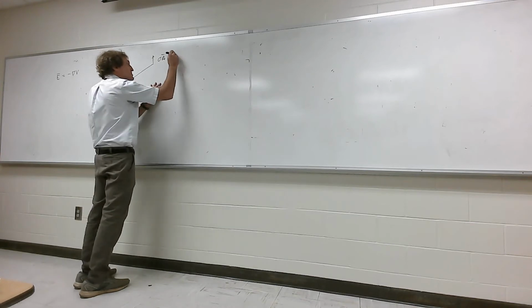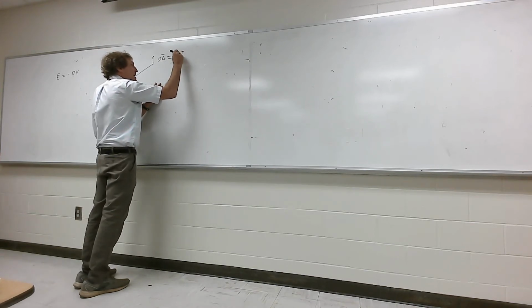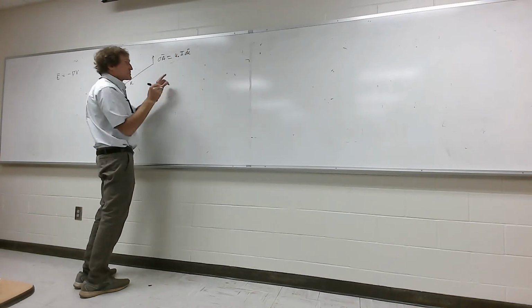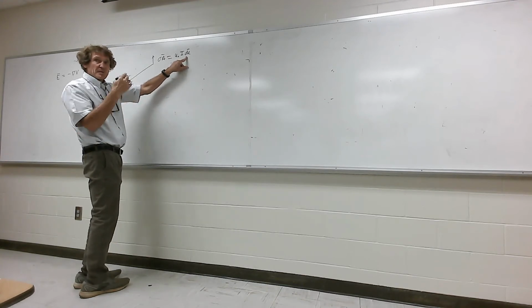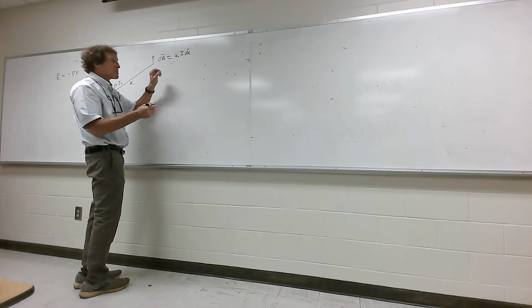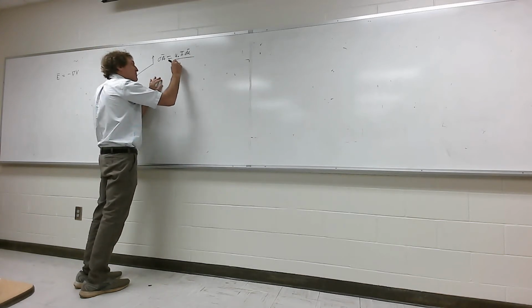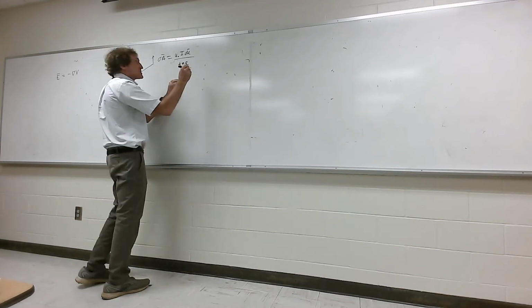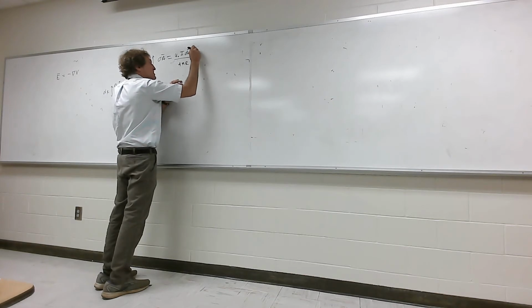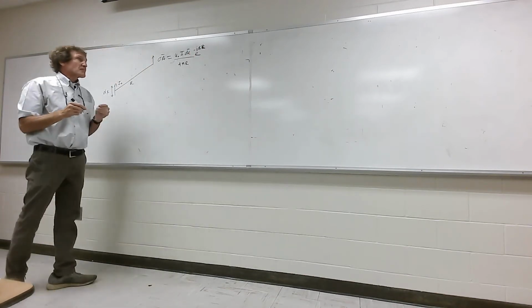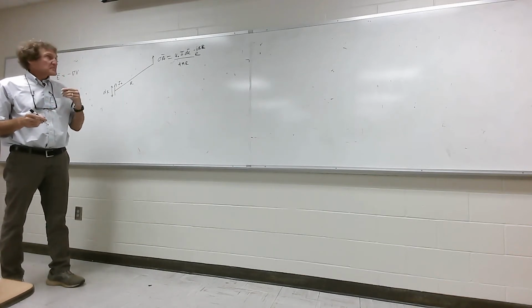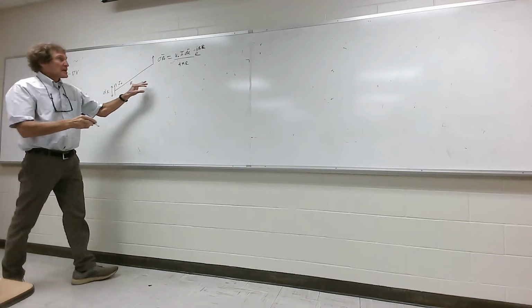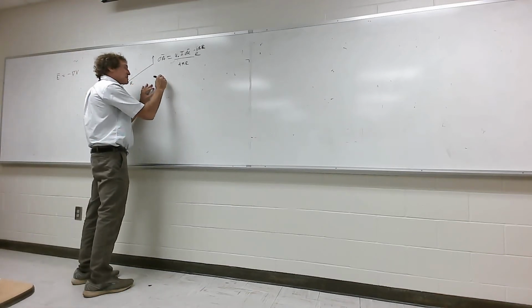dA is simply equal to mu0 times I dl. It is a vector, so the dl has a vector sense to this. If it was in the z direction, it'd be dz az. You all follow? It's going to be divided by 4 pi r. Then it's multiplied by e to the minus j beta r. Now that's the actual magnetic vector potential, but it's the differential of it, the total A field, e to the minus j beta r.